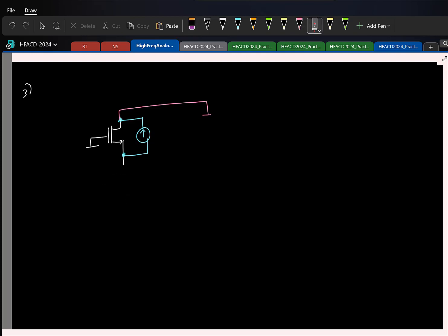So what is the portion of this current that flows to the output? 0. Essentially the cascode transistor contributes 0 noise, provided the bottom device has infinite output resistance. If not, it will get attenuated by a factor of the order of 1 by gmR0. So that's why cascode is a nice thing. This guy silently comes without making any noise and helps to boost your gain.